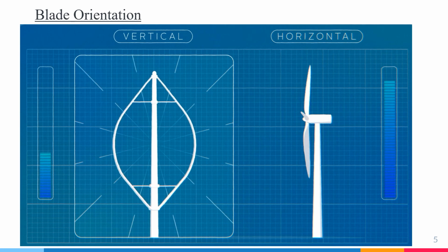A rotor with an odd number of rotor blades and at least three blades can be considered to be similar to a disc when calculating the dynamic property of the machine. A rotor with an even number of blades will give stability problems for a machine with a stiff structure.